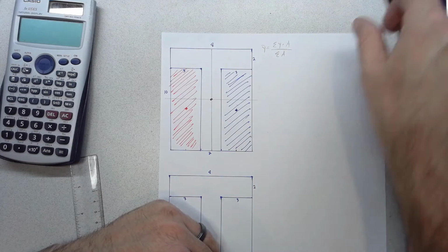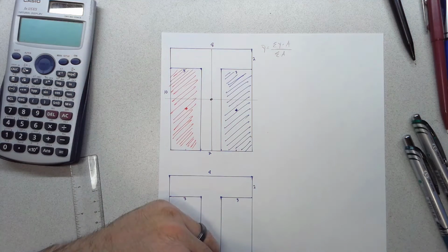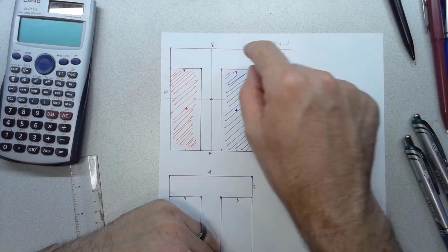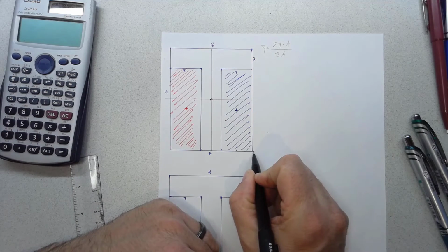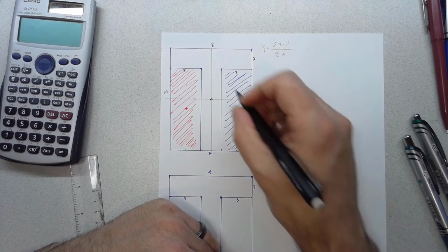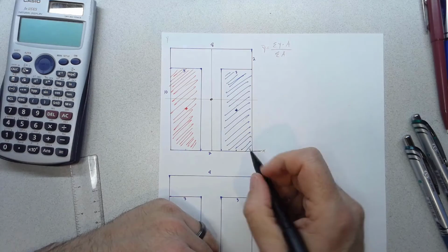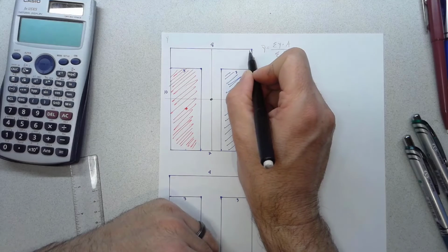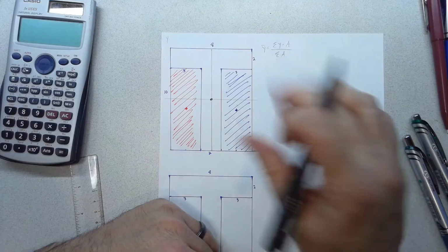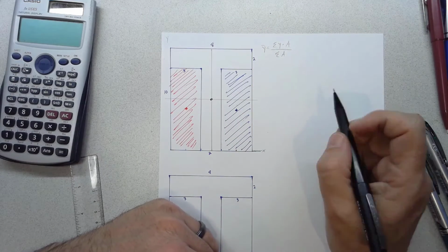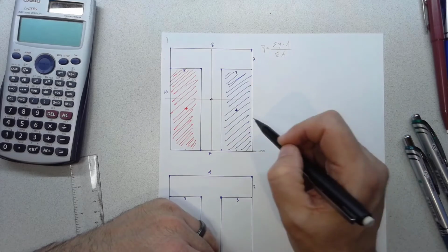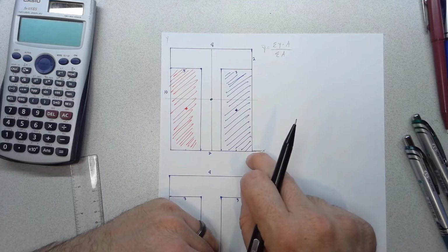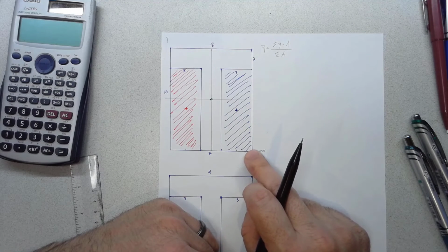So let's look at that. Let's break this into pieces. We want to find y bar for this composite piece. For me, I always make my reference point for finding y bar from the bottom of the shape. You could do it from the top here. It shouldn't make any difference how you do it. You can go back and look at the centroid video if you don't believe me or don't remember how to verify that you can do centroid from either direction. So I'm going to use my reference point here at the bottom to find the centroid.